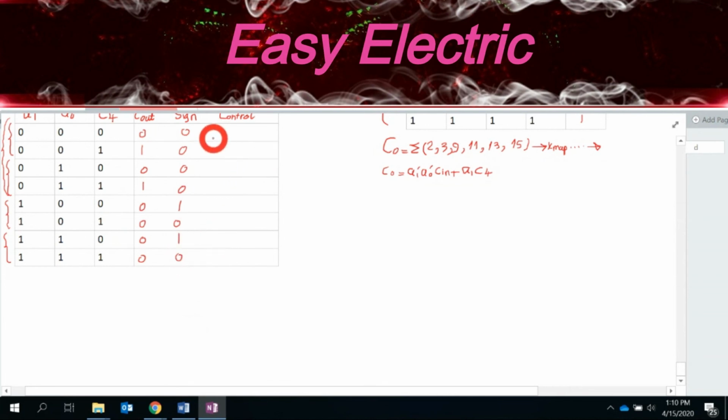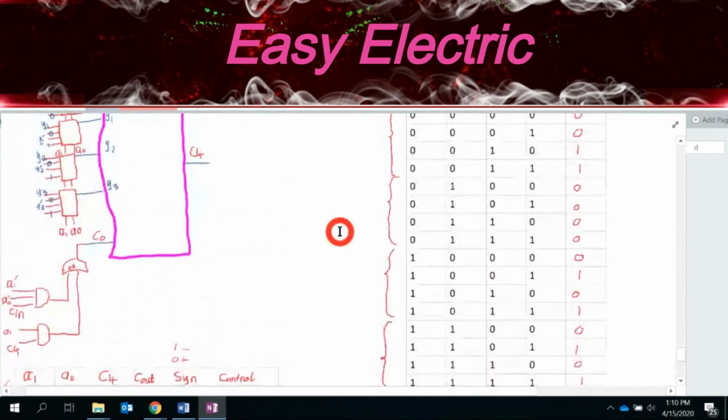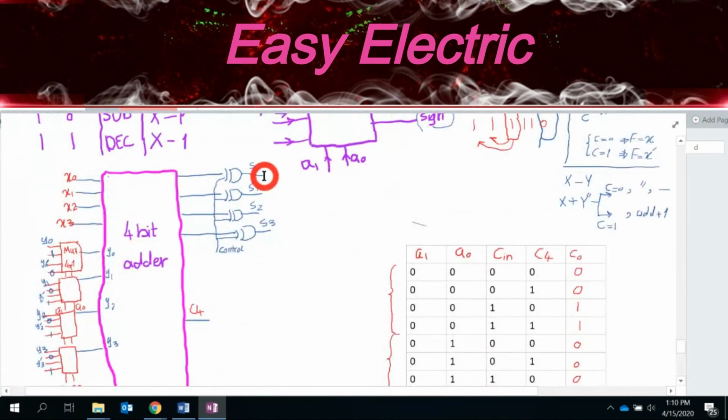So that's actually for the sign. How about the C control? So back here, when we should have the numbers without the prime, the control is C0, no prime. Where we should have no prime depends on C4, right? So if C4 is 0, you need to take a prime. That means C should be 1. Whenever C4 is 1, you don't need to get the prime. You should have all S. So that means C0 should be 0. So let's start first with whenever we don't want the prime. So the C should be 0.